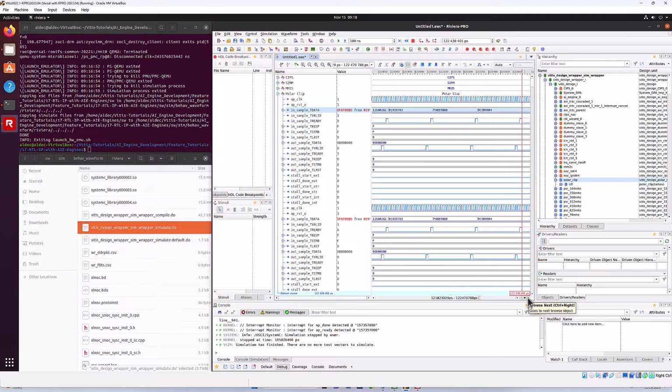Okay, you can also view the delta cycle in the transition there. So here in this transition, there's 3 delta cycles there. What about the next transition? So there's also 3 delta cycles. So you just kind of keep browsing. Click this again. All right. So it looks like there's about 3 delta cycles that happen during each transition here. So let's remove all of these delta cycles. Okay. Now let's focus our debugging here in the out sample T data.